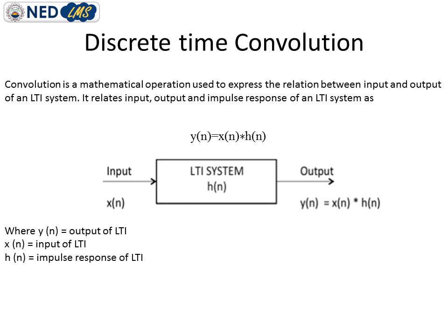Summarizing our discussion for understanding how a system changes an input signal into an output signal. First, the input signal can be decomposed into a set of impulses, each of which can be viewed as a scaled and shifted delta function. Secondly, the output resulting from each impulse is a scaled and shifted version of the impulse response.